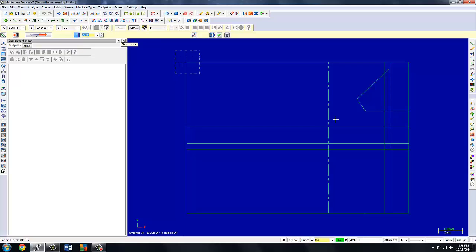at the lower part of the profile. Accept that. Go back to my line endpoint. I see I've got one at 10 degrees off of this intersection, so I'll put that in. 10 degrees is actually 90 plus 100 in this instance, so there's my 10, and I'll just place it randomly, accept it. I have another angle that I really don't know what it is, but I have the intersection point, so it doesn't matter, so I'll place it there and there, and accept those lines.